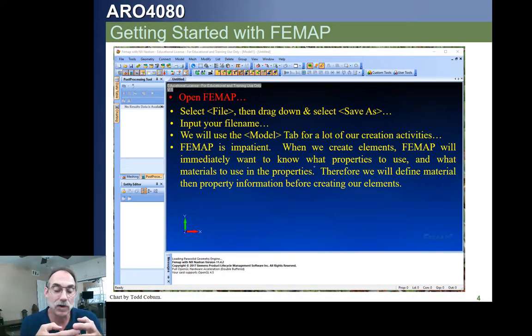Where NASTRAN was pretty simple, when you work right in the NASTRAN deck, you can use the same basic case control deck and executive deck for most models with only minor tweaks. Now we're going to have to go through this picking process. We're going to have to pick a lot of things, and a lot of that's going to ask for capability that we just plain old don't need. So we're going to have to go through that systematically and keep alert to the different kinds of things we can do. Okay?